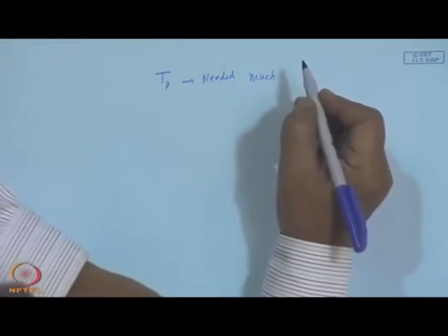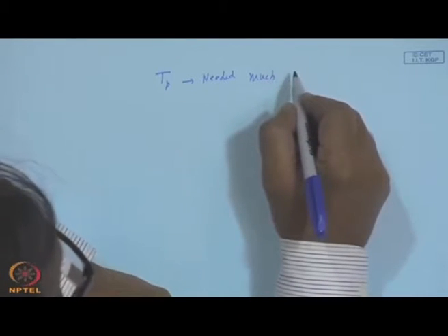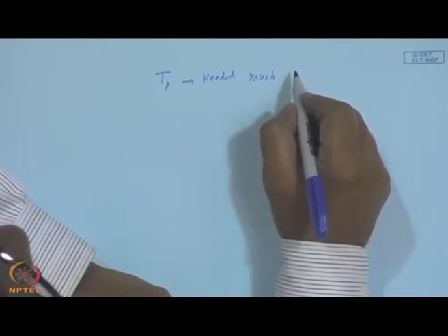If you are comparing an absorber which weighs 10 kilograms to an absorber which weighs 2 kilograms, with, let us say, specific heats being almost the same or 1/2 or whatever the ratio, the m C p ratios. Now, if you have got an m C p 10 times that of the other, then the energy required to heat the absorber to the desired temperature to deliver energy at the desired temperature will be much larger.